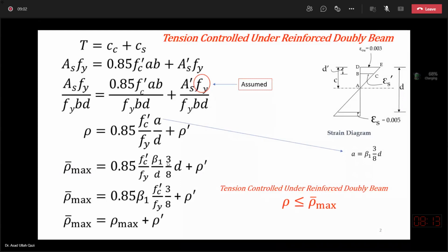So in classification with rho, we also want one rho equation which will tell us whether it is a case 1 or case 2 doubly reinforced beam, so that without going into comprehensive review, just looking at the rho and comparing it with some typical rho will tell us that compression steel will be at yield or will not yield.